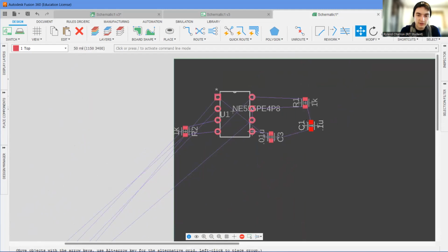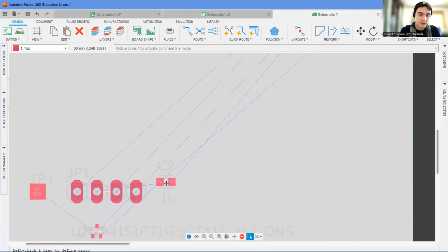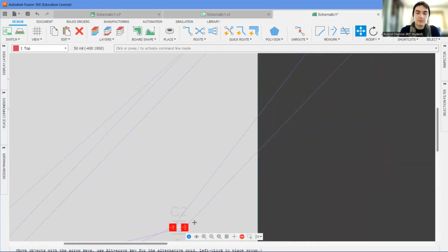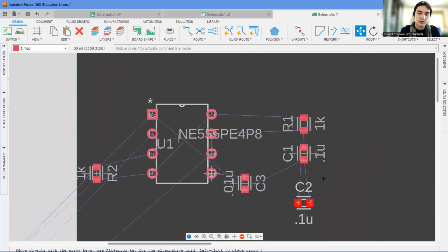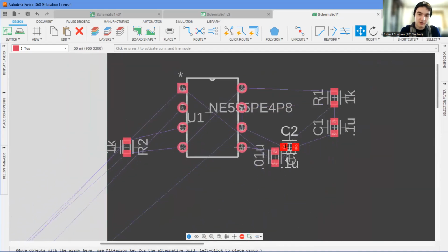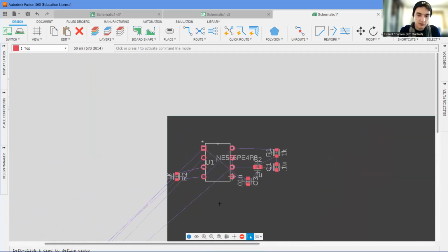We would rather have this with our useful resistor, and then the ground connections will come later. With the schematics and the PCB, I do power and ground usually towards the end, just because there's so many different connections that are power and ground. If you try to individually do all of them, it'll take actually forever. So let's see, we got this guy going to ground as well. So we're just going to stick it near the pin it cares about.